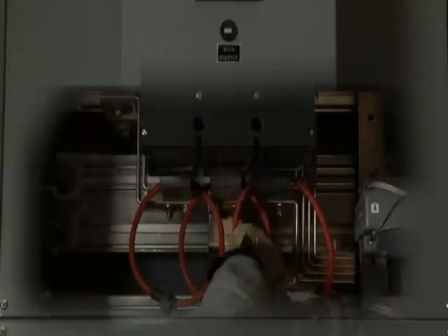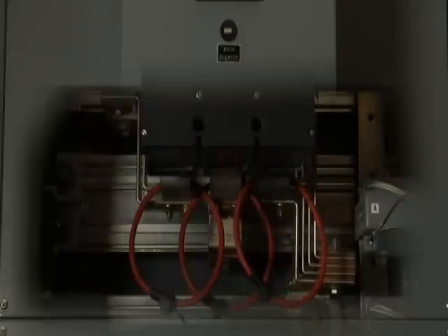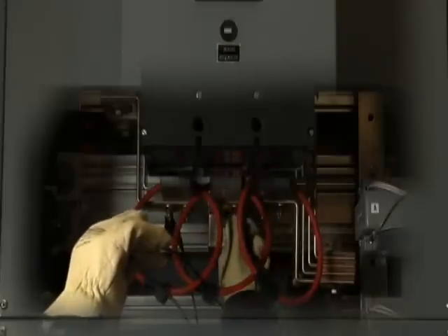When you do this, you will most likely be lying on your back in your flash suit, wearing your gloves, reaching up to connect, as you can see here. It can be awkward, so be careful and follow safe work practices. Be especially alert for extremely high arc flash incident energy levels at service entrances. You may have to go downstream after the service disconnect or main breaker to log values.